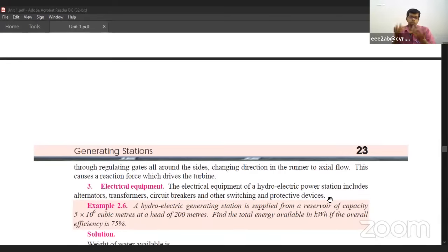So those who are using three phase supply, you will be finding in your panel board your energy meter. There will be some three phases in some other meters, okay, that will not be given by your electricity board. So you have to install separate meters to see which phase is on. Say for example, RYB three phases, which phase is on during the particular time.